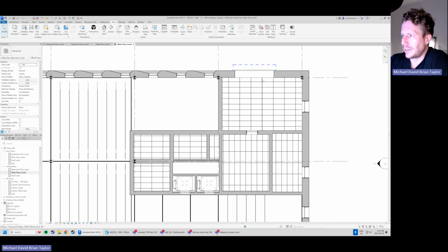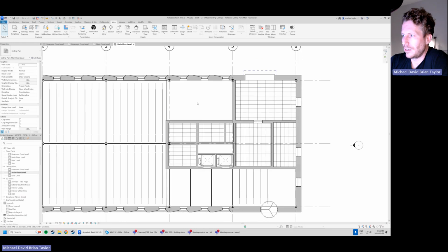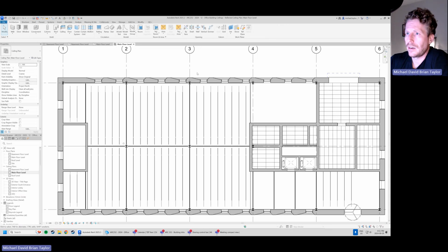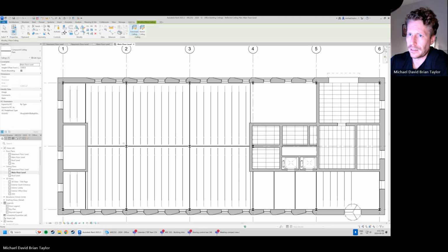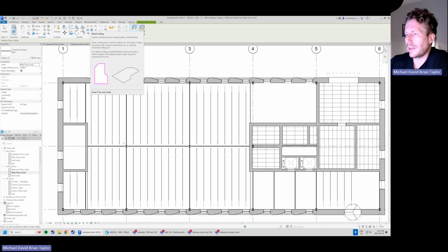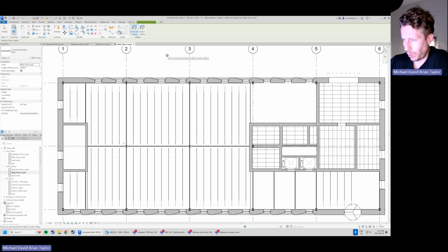And why don't we go ahead and jump into the sketch tool here. So let's jump into the sketch, and if we jump to the architecture ribbon and then go over to our ceiling tool here, click ceiling. Now the difference in this exercise is that we do really want to sketch the ceiling rather than automatic, which again takes the walls. It's going to let us draw basically a frame or a zone, a loop where we would like to have a ceiling. Again, I haven't given us dimensions, so I encourage you to try this out. It does not have to be perfect.